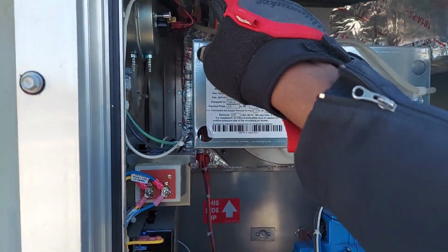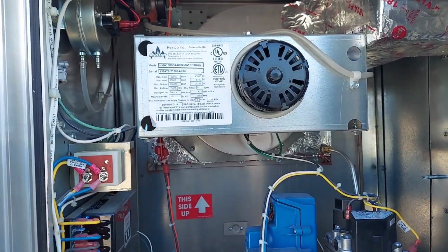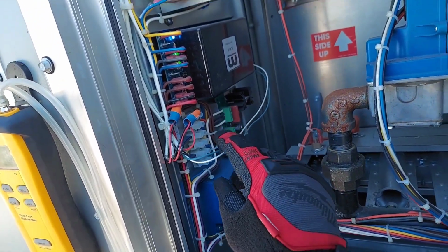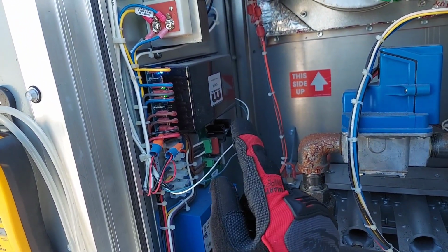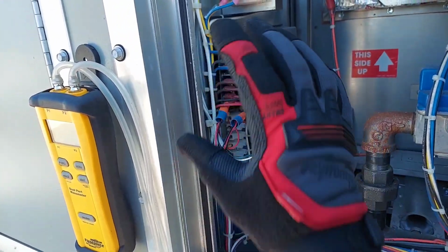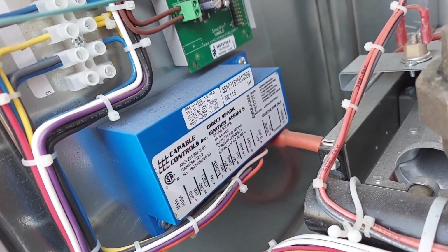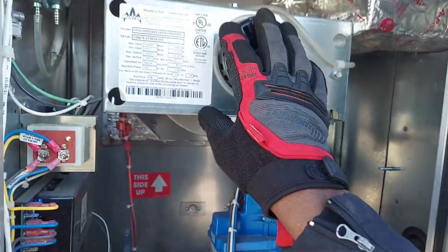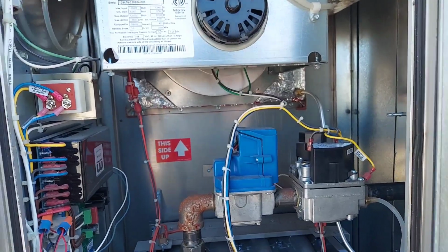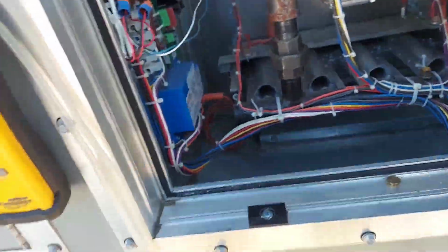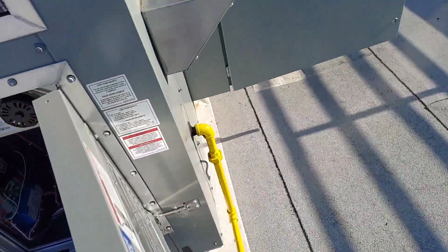So yeah, you got 2 airflow switches because one is for high fan, one is for low fan. So there's 2 of them. And then again, the controller over here takes care of all that. This is where your signal comes in. Right now, for 25%, you're getting 2.5 volts DC coming here. And this does all the controlling. And then here's your ignition module. Ignition control module, that's a fan board that controls the speed of the combustion motor or induction motor. Furnace exhaust fan, flue exhaust motor, whatever you want to call it. Many names.